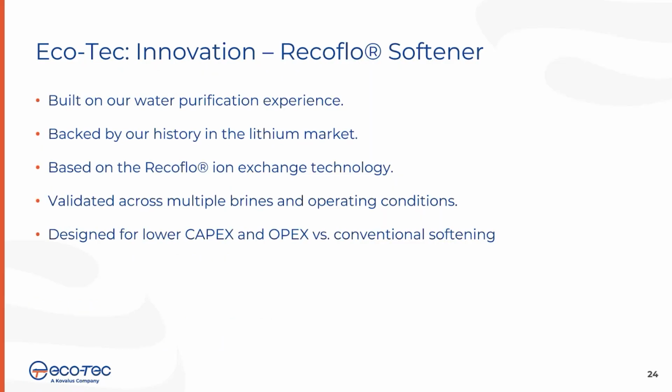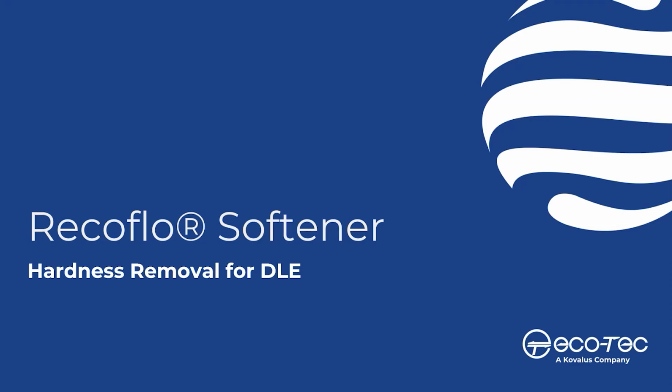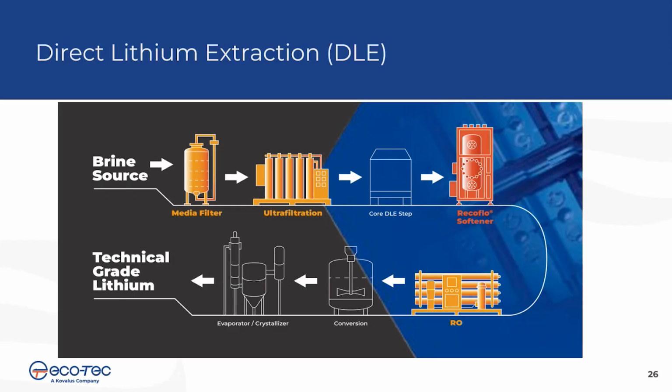Recoflo softener leverages our water purification experience with our history in the lithium market. It's validated across multiple brine and operating conditions, and it targets a compact footprint with improved efficiency and lower operating costs versus conventional softening. Now that the technology foundation is set, we can move into the details of our Recoflo softener. To place the softening correctly, I will first walk through the DLE flowsheet at a high level.